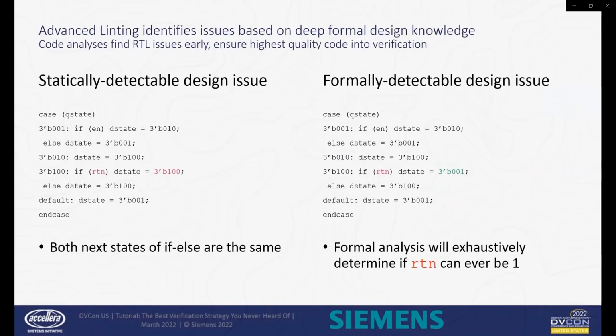Advanced linting tools build on simple static lint concepts and serve an important role in intent-focused verification. Providing deeper insight than simple static analysis, these tools are able to leverage their exhaustive exploration of the design state space to identify issues that would not otherwise be apparent. Equally important, these tools are able to eliminate false violations, allowing the team to focus on real problems.